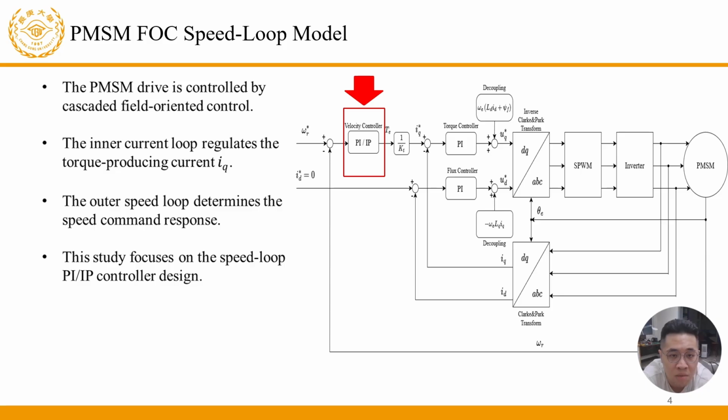In the simplified model, the speed command goes into the controller. The controller outputs the current command. This current produces torque through the motor constant. Then the mechanical system converts torque into speed.